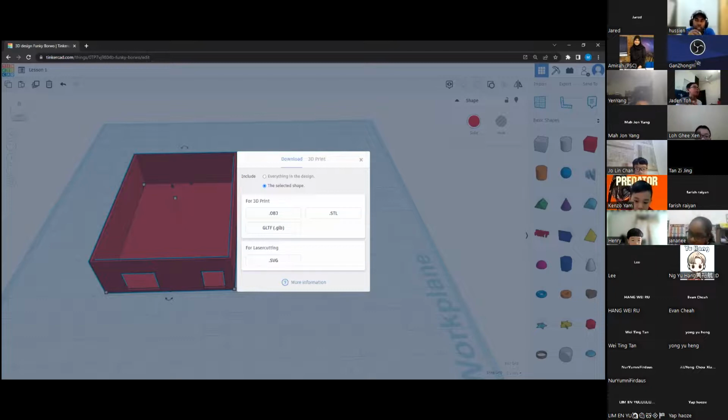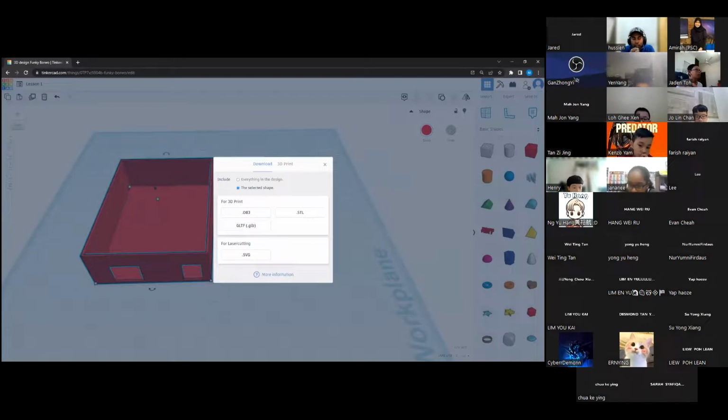Before we get the G code, basically, when Cura generates a G code, during that time it will mention how much filament will be used. In TinkerCAD, we will not be able to know how much filament we'll be using. So that one we need to see in Cura. If we have time, then later I'll show it as well.